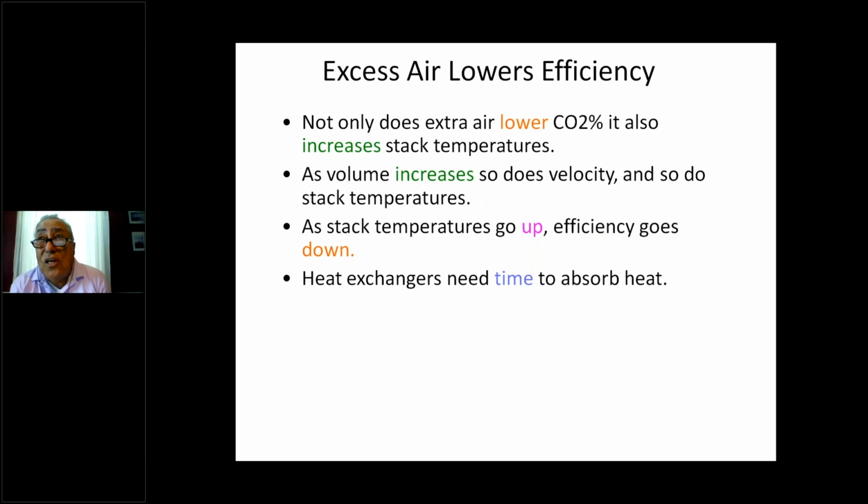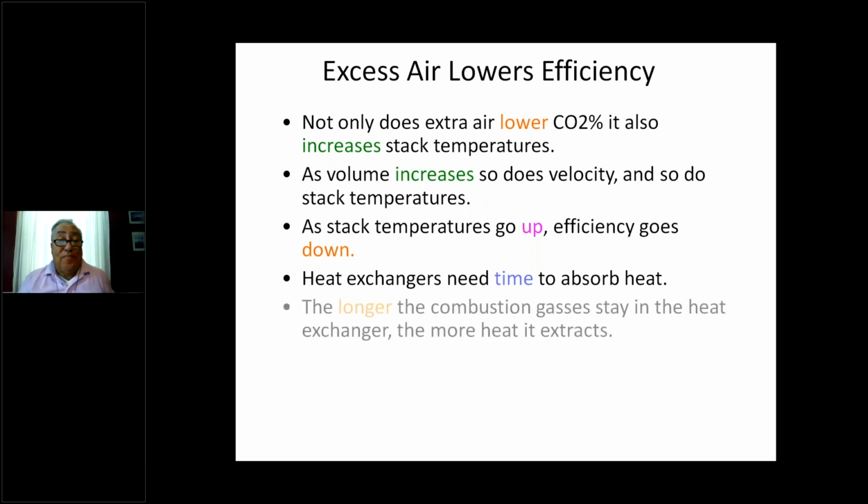When we're looking to adjust the draft, we want to keep that draft down to slow that flue gas down from whistling through the appliance to keep it in the heat exchanger longer. So the simple fact here is the longer the gas stays in the exchanger, the more heat it extracts. It's that simple. Excess air has everything to do with not only the efficiency, but then that stack temperature.